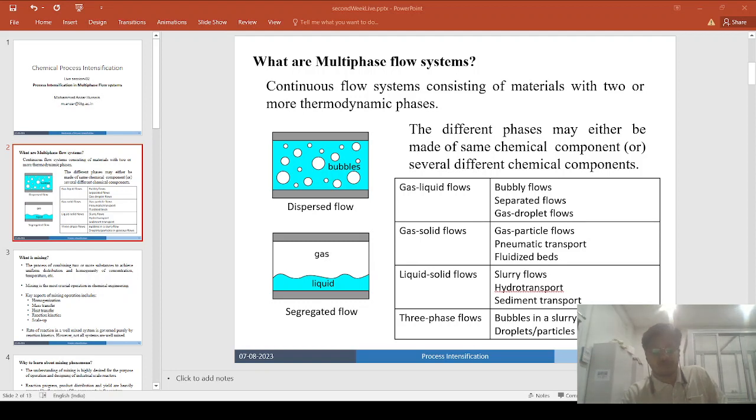So for example, in the case of heat transfer, whenever there is an interface, the boundary condition applicable at the interface is the continuity of fluxes. For example, if the heat transfer is happening in one dimension, in the x direction, then dT/dx must equal dT/dx at the interface. So yes, the fluxes should be equal.